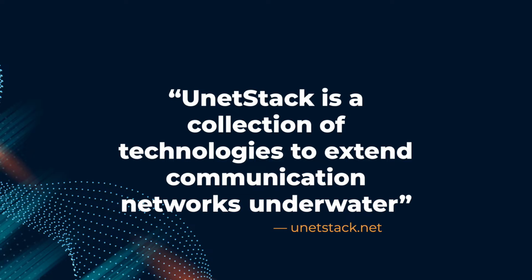So earlier in the talk, John was mentioning that, yeah, you can send sail drones to wherever, and I can be at my office, look at whatever it is they're doing happily. But what about AUVs? I also want to do the same thing with AUVs, right? So AUVs or any kinds of vehicles can also send this kind of information, maybe images, depending on the speed of your link, maybe some sensor data to a surface, and you can have a gateway buoy that converts from sound to RF and then sends it back through Iridium or any kinds of similar technologies, Wi-Fi or GSM, back to your office so that you have the full end-to-end connectivity completely transparent.